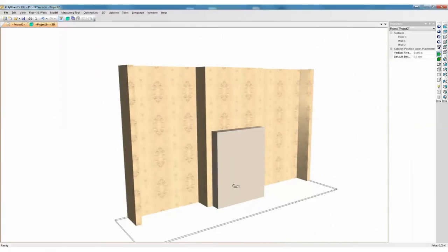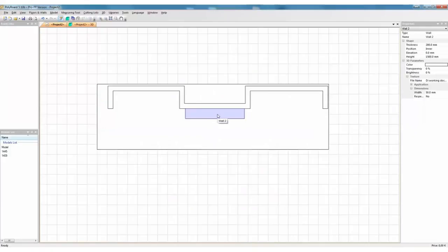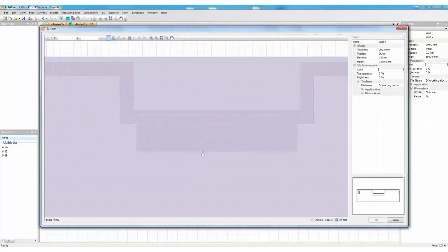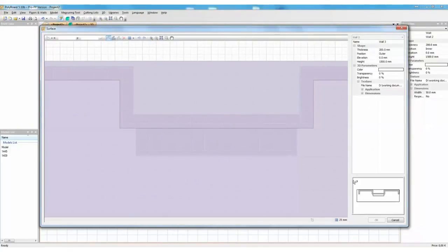Now let's hollow out this fireplace to actually give the hearth of the fire. How do we do that? Well, in the project mode again, I will click add a new wall again. It's the same thing, I don't really care where it is because it's only a matter of quick representation. I'm going to draw a new wall, and this time I'm going to click the wall approximately the position that I want the hole.